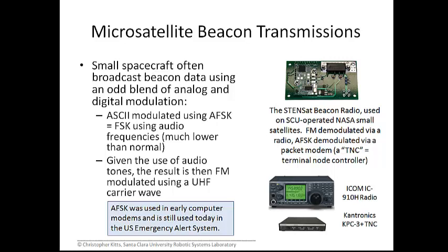So we're shifting the frequency of the UHF carrier wave, and typically the frequencies we have for our beacons are sort of clustered around the 435 megahertz point, plus or minus a megahertz. Most of the center frequencies are in that range.